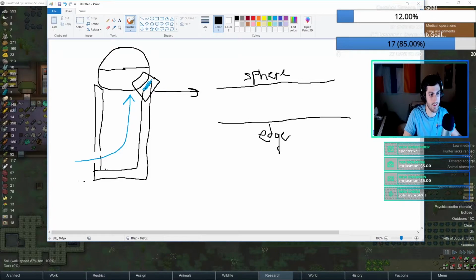So when you expand it out to look at just this area, it's such a small part of the sphere that it's about linear. And so when we have fluid flow like this, ignoring the fluid falling, we get what's called a parallel plate fluid flow. So if we assume that it's not turbulent, because that complicates a lot of things, and I don't know how to do that yet, and then we take a line of fluid, what happens is we get something parabolic, and it has 0 here and here.